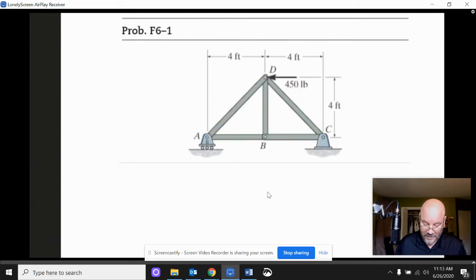The thing that's happening to the triangle is we have an applied external force and then we have reactive external forces. Here at A, it's a roller bearing. To me, it looks like little roller skates on that thing. So it could go back and forth, but the point is that A can only provide a normal force.